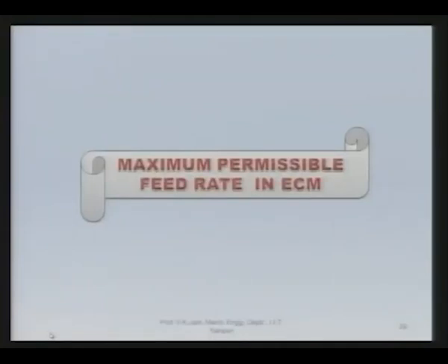very important. If the feed rate is very low, then productivity will be low, and accuracy will also be low. If it is very high, although the material removal rate will be high, there is every possibility that a short circuit may take place, and that short circuit will result in damage to the tool as well as the workpiece. So, let us see how to evaluate the maximum permissible feed rate for the given machining conditions.